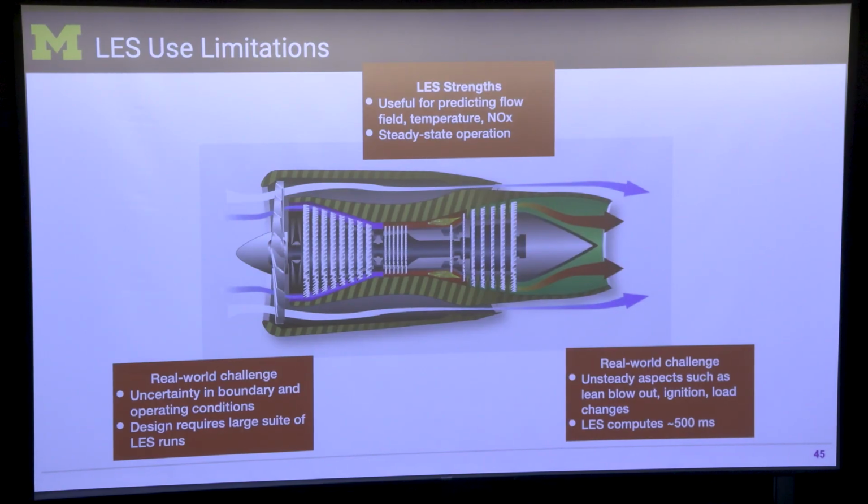There are so many examples. If you go to industry, you ask any of them, they'll give you so many examples of how before they had LES, their ability to predict what they call smoke number, which is how they characterize how much emissions they have, was so much more difficult than after they had LES, and things were just magically better, right? So for those kinds of predictions where small-scale physics dominate what happens, LES is very good, and this is where we should use it. Now, there are other problems where it's not very good and introduces other kinds of issues.